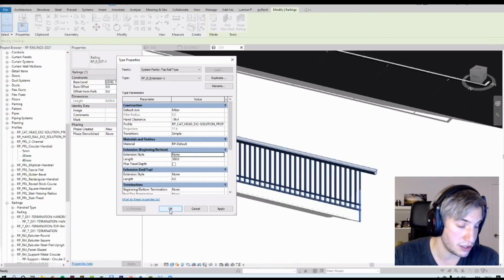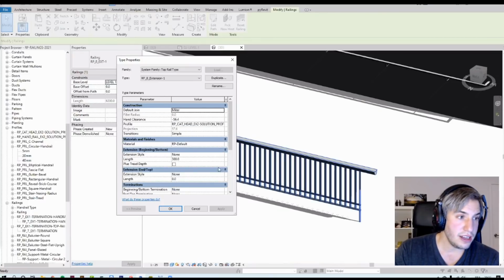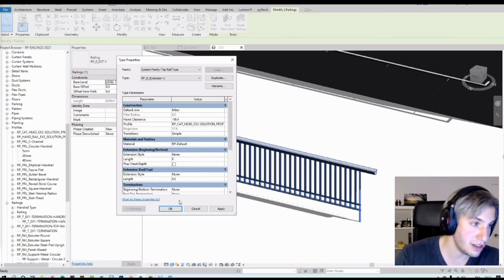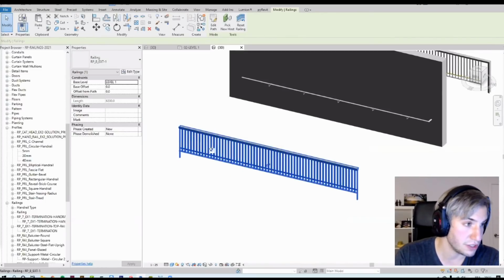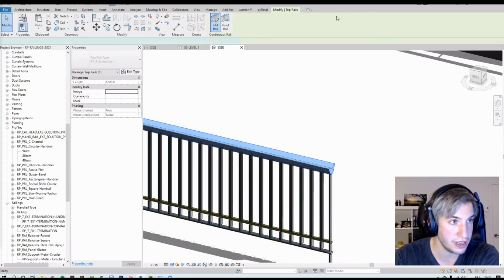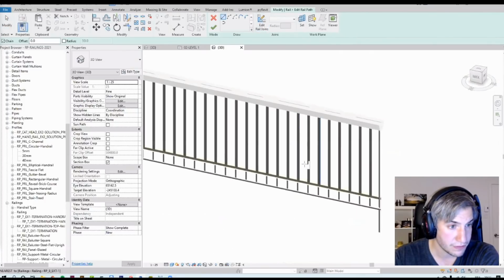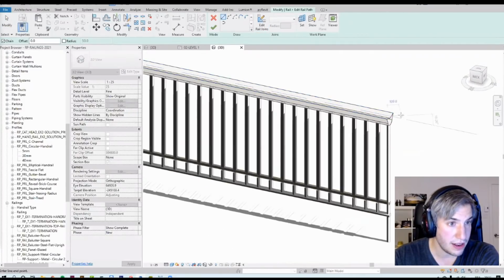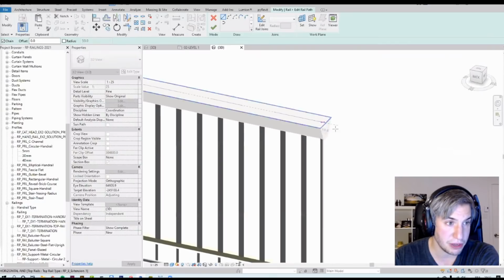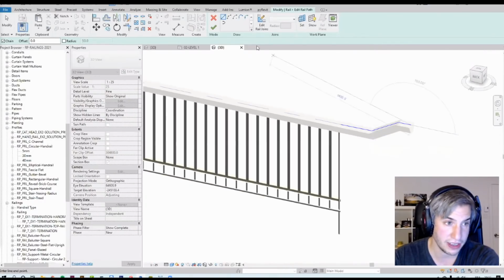And that's just opening up the door for you to edit the profile of it, if you wanted. But you don't have to. You could completely remove the value here, so just a basic normal railing. And if once again I go to edit the rail, click path, you can draw it as long as it's not within the magenta sketch lines, basically. That's right.